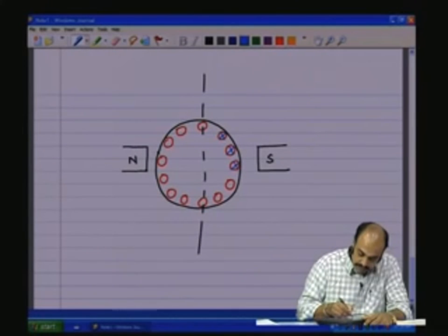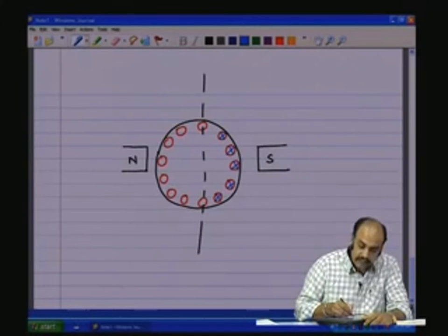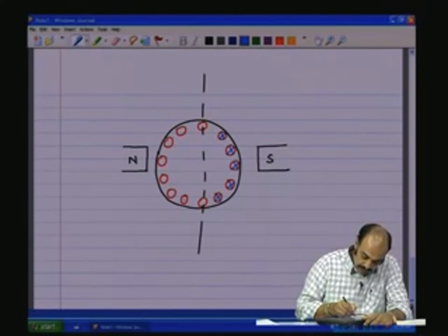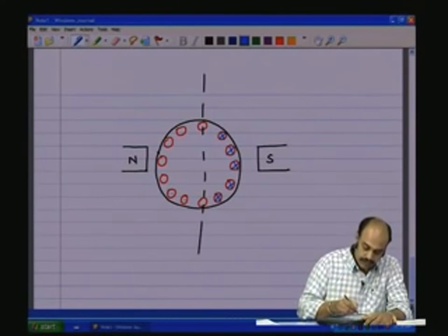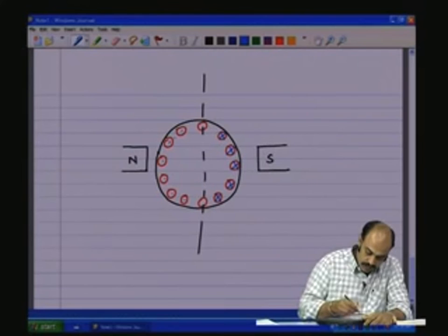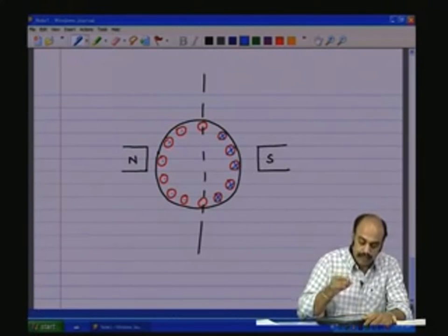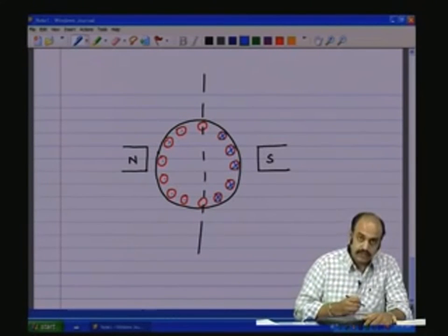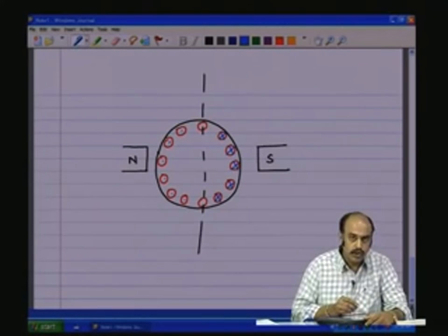All these will be in the same direction with magnitudes varying. The one which is nearest to the south pole will have the largest magnitude. So, again this conductor is going to have zero current because it is in the neutral zone, and then here the direction will be opposite, coming out of the board with varying magnitudes. The one nearest the north pole is going to be having the largest magnitude of the induced current.